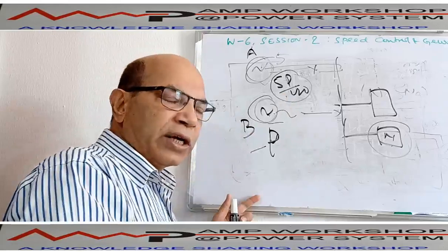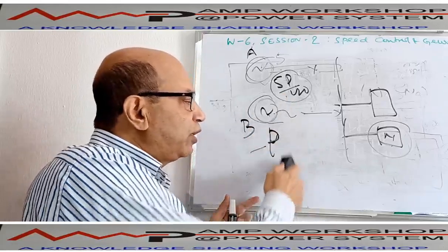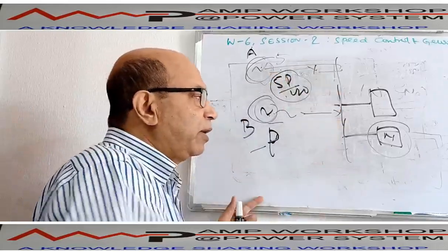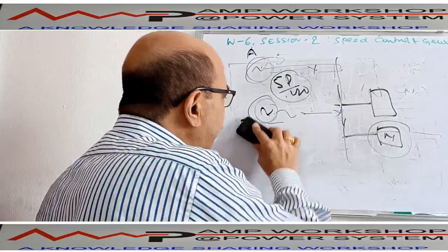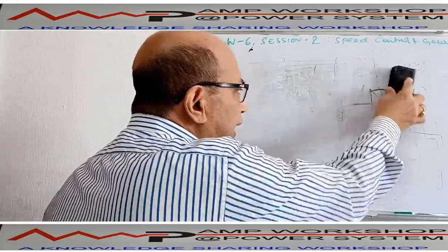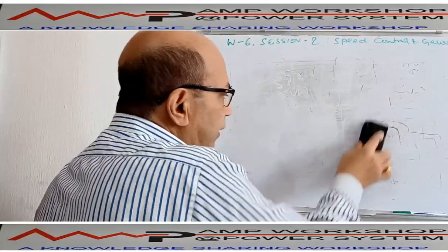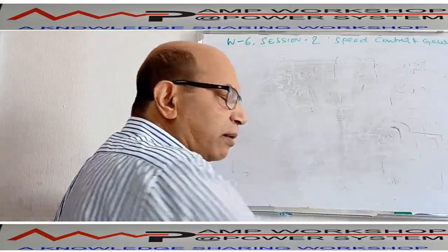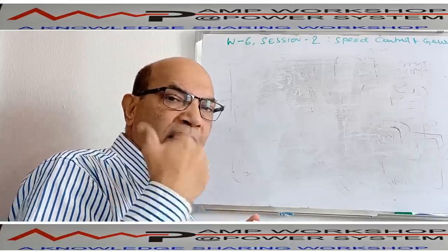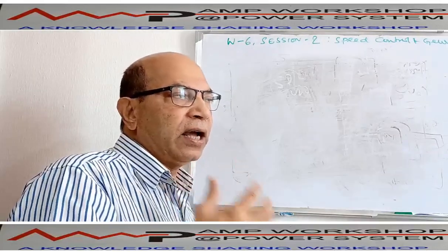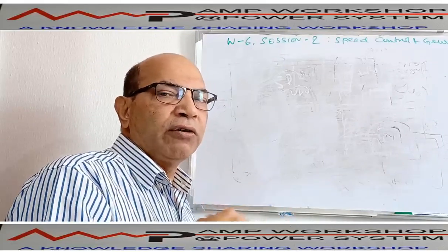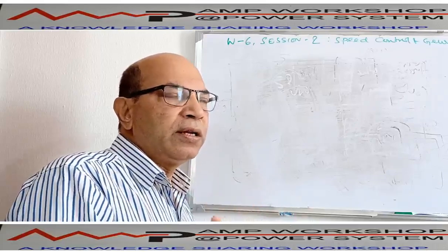Other machines we operate, generally, if there are multiple smaller machines, we put these machines on Droop mode, and the big machine we put on isochronous mode. It will maintain the bus frequency. So this is the isochronous mode. Now in case of Droop mode operation, when the machines are not identical, and when the machines' governor systems are also not identical, or if the machine is running in parallel with the grid, in that type of operation, we cannot run the machine in isochronous mode. I said why? Because they will compete with each other and the machine will go into unstable operation.